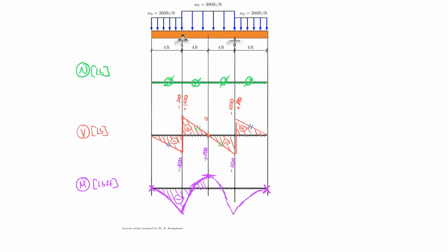And that now gives me my entire diagram, which is negative here on the bottom as well, because I have the very same physical behavior on the right side. Everything here is bending downwards. So here the beam is frowning, and it's actually frowning all the way up to here. So this part is frowning or bending downwards. This part is bending negatively or frowning, or the top is in tension. Whereas from here to here, the bottom is in tension and the top is in compression.